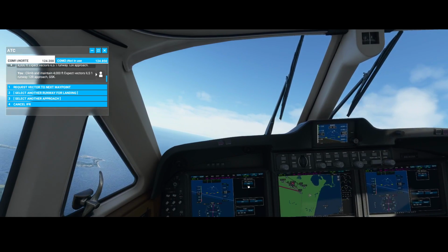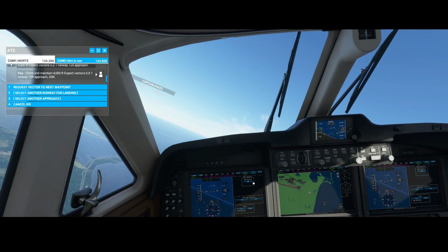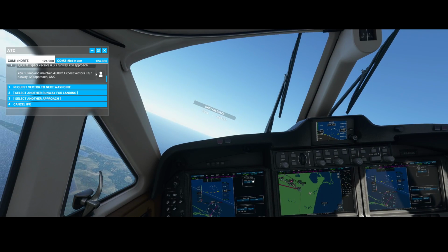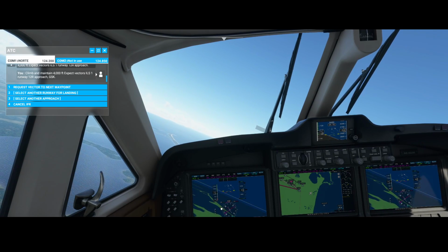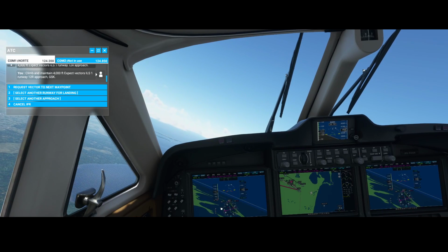You already probably know what I forgot. I forgot to set it back to FMS. So make sure that if it's set to VOR 1 or VOR 2, you're changing it again to FMS, because else it won't use it. So we're gonna turn the airplane. I will go on mute unless something goes wrong.